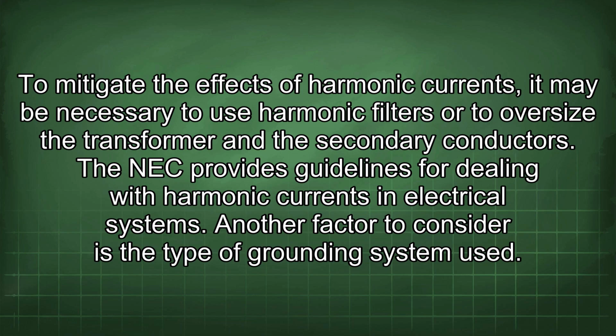To mitigate the effects of harmonic currents, it may be necessary to use harmonic filters or to oversize the transformer and the secondary conductors. The NEC provides guidelines for dealing with harmonic currents in electrical systems.